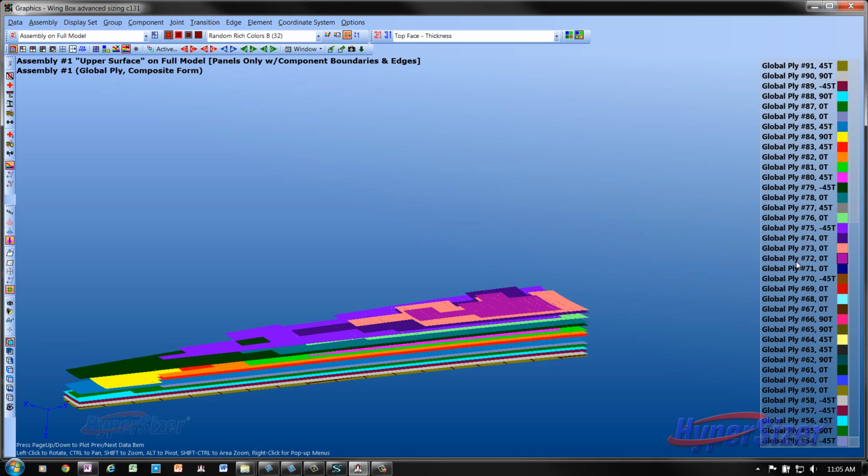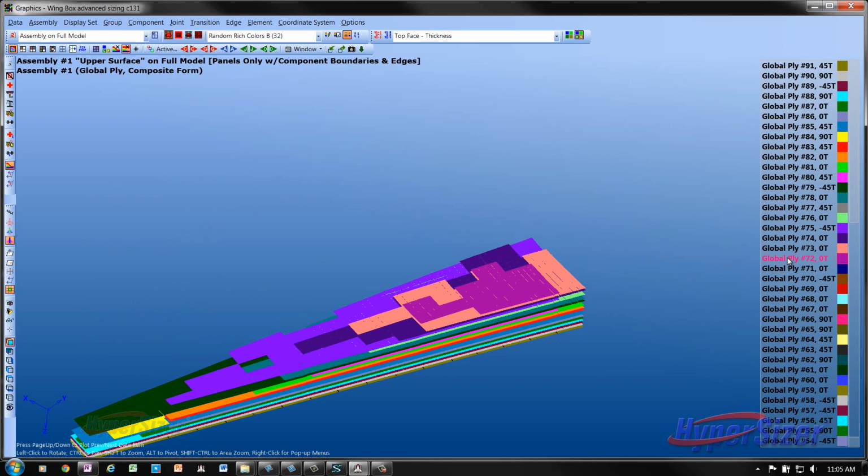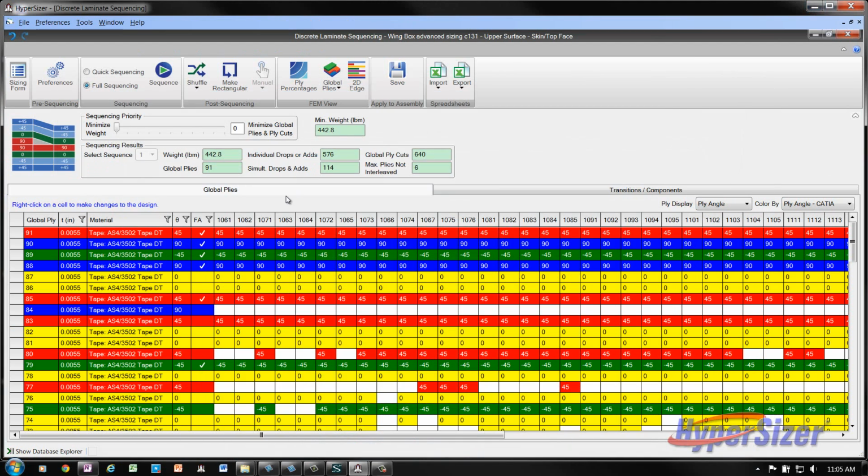You may notice that if you stop right there, you see a non-rectangular type view of the way the pattern is being developed here, like a jigsaw puzzle. There's one additional feature that you may want to use, which is to make rectangular. The wind blade manufacturing industry likes this feature, and the purpose of which is, without much of a weight impact, to take away the zigzag pattern in the layups and make them more square.